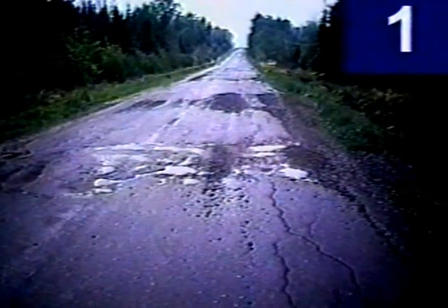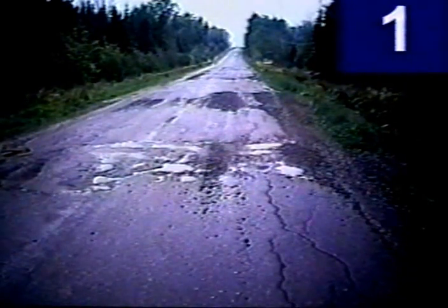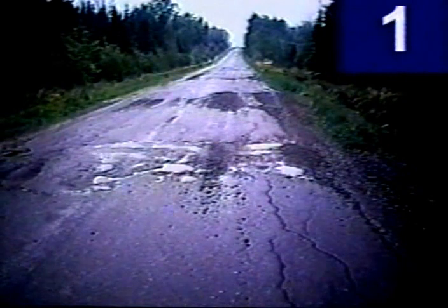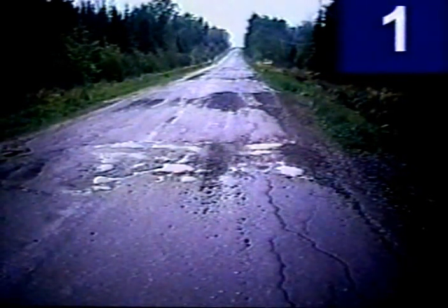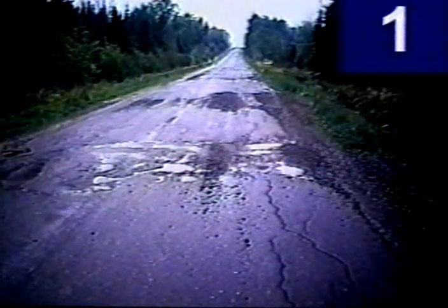If we move now into our lowest category, pavements rated 1, we're talking about total failure. You can see here that the roadway is broken up, water standing in the road. You have traffic that has to proceed at a very slow speed. Looking at total failure, that's why I would rate this a 1.